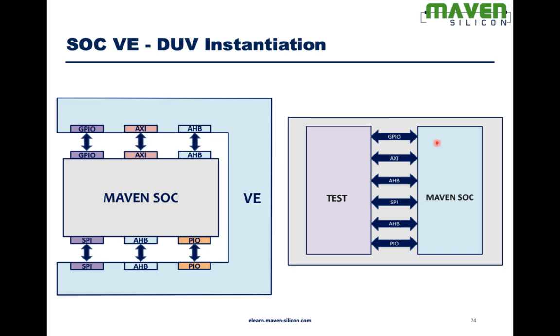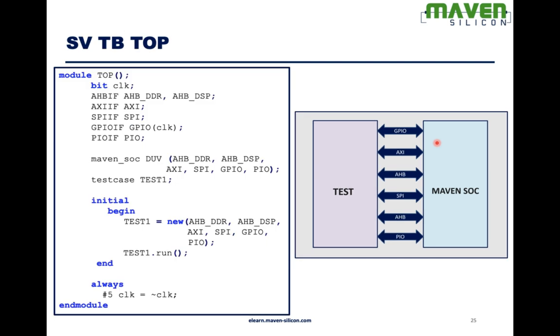And the other important thing is this interface works only when you have similar ports. You can connect AXI with AXI, AHB with AHB, SPI with SPI, UART with UART. But you can't make connections like AXI to AHB. Interface will not work. Always remember this. That's why this can be applied beautifully for the SoC design. But if the design is going to have different kinds of protocols, custom protocols like protocol 1 to protocol 2, then the interface will not work. You always need to remember this.